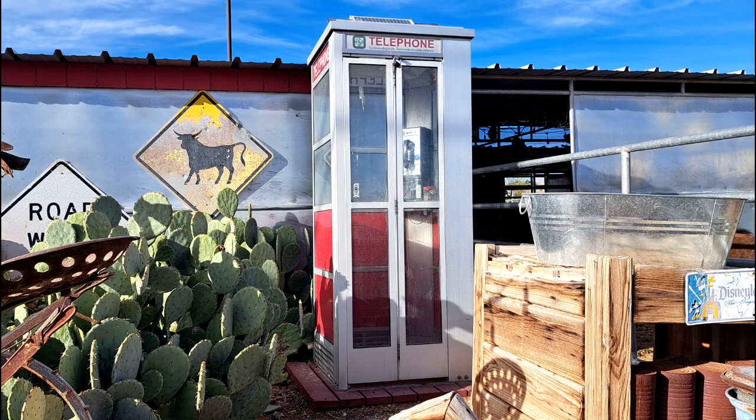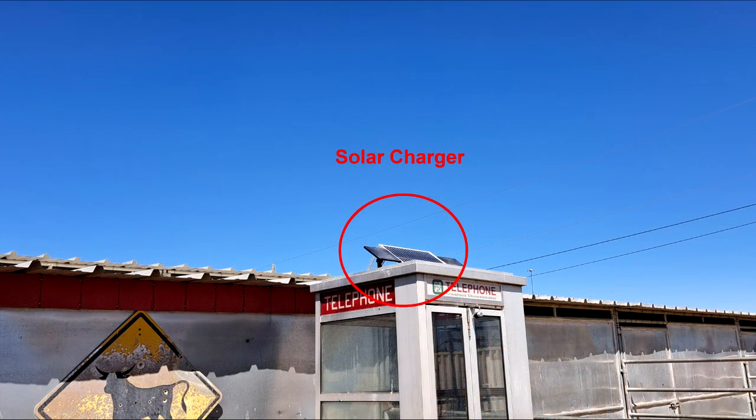If your payphone will be located in an outside or remote location without available line power, you will need 2 additional components to keep the battery charged. The first is a 12-volt solar panel. These are often rated at around 13 volts, which is fine.